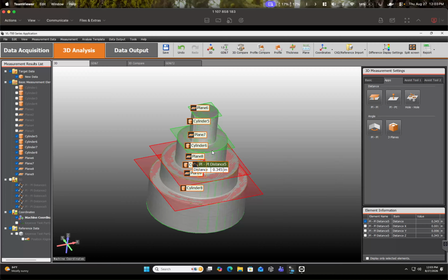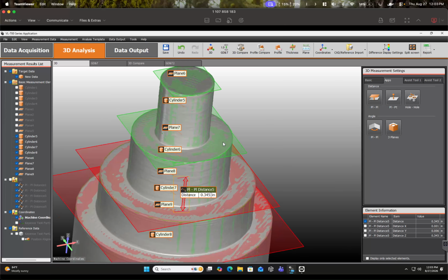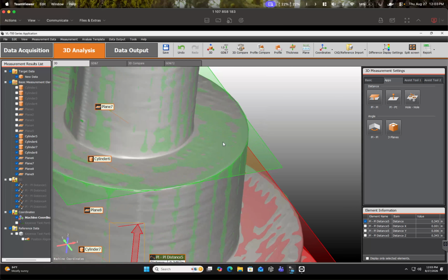These dimensions and diameters that it's given us are averaged out, and it's placing cylinders and planes of best fit. But if you zoom in on it, you'll notice that you can see the bump pattern of the surface, and you can see the imperfections of the surface. So if we want to actually see how different the change in tolerance is with each of these lumps that you see here, or this is what's called the Z seam on a standard 3D printer.